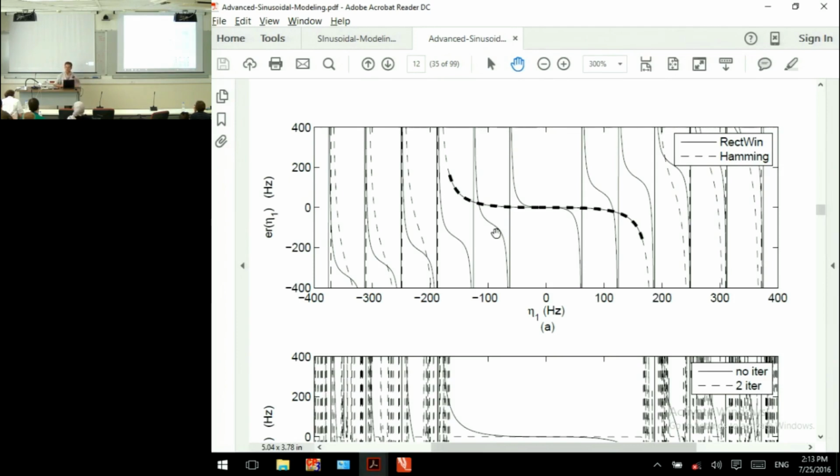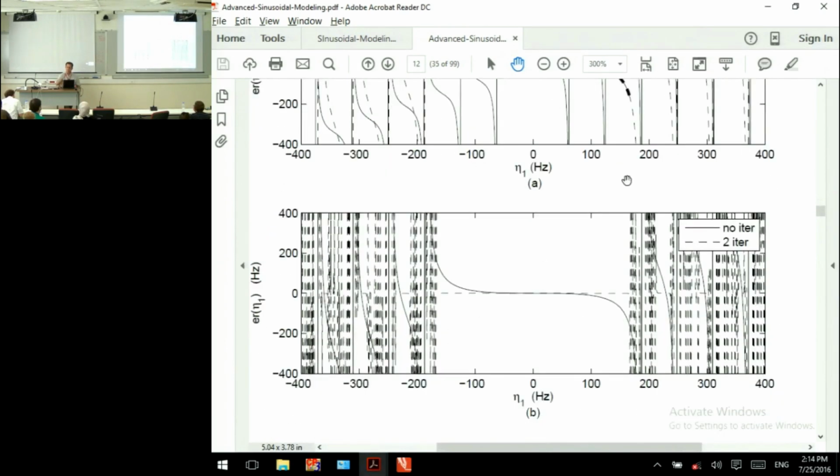Now, the good thing is that you can probably have a way like peak-picking to try to find something better. And indeed, if you don't have noise, a peak-picking method can correct also. If I tell you it is 1,200 hertz, and then you do a Fourier transform and peak-picking, you say, no, it's around 1,000. But that peak-picking has no mechanism. You have done that, it's over. This has a mechanism to repeat, to do iterations.